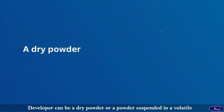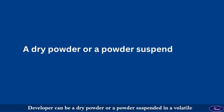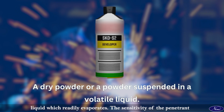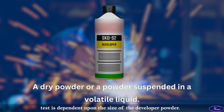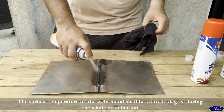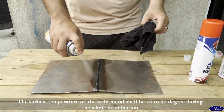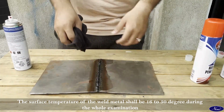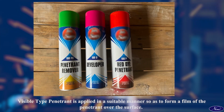Developers can be a dry powder or a powder suspended in a volatile liquid which readily evaporates. The sensitivity of the penetrant test is dependent upon the size of the developer powder. The surface temperature of the weld metal shall be 16 to 50 degrees during the whole examination.